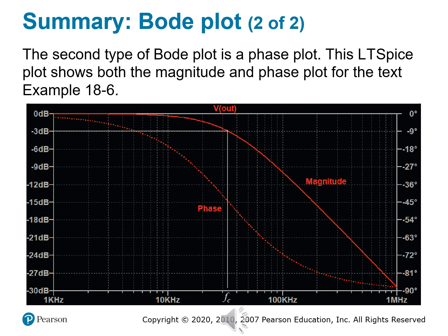As frequency increases, the phase of the output voltage lags behind the input. It starts close to 0 degrees, then dives to that negative 90 degrees as we approach those higher frequencies. And this phase information tends to be critical when timing really matters, like in communication systems or analog signal processing, because phase shifts can cause distortions or even cancellations when you have multiple signals combined.